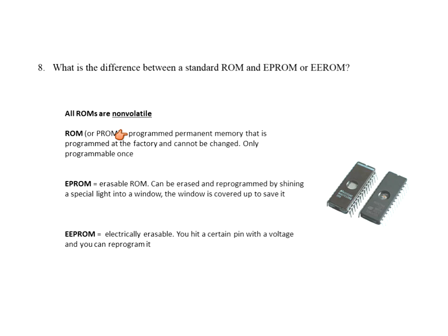Now, you'll hear some people say there is a difference between PROM and ROM. Well, there is a little bit. PROM sometimes, if you are a company, you can buy a ROM chip and program it yourself, so they'll call it a PROM. Sometimes you buy the chip from the factory and it's already programmed. It just depends on who you designate as the factory. So you cannot write into a ROM. It comes pre-programmed. Compared to a RAM, you can write into it.